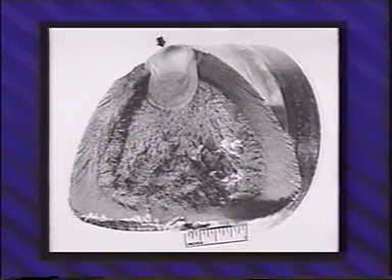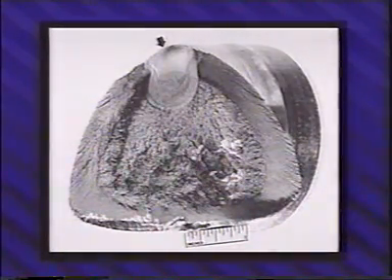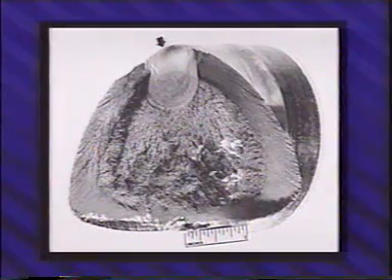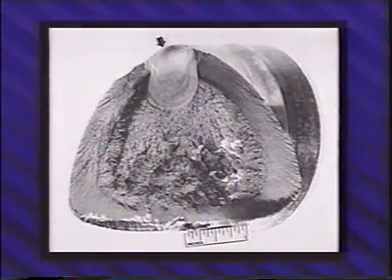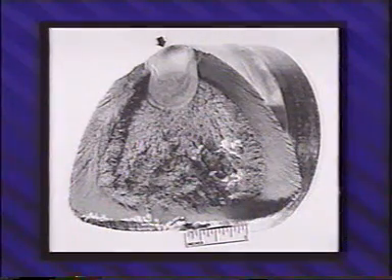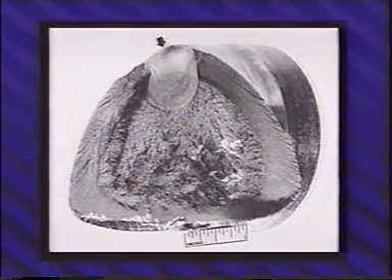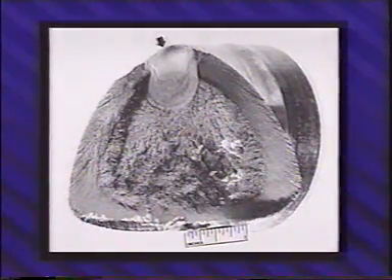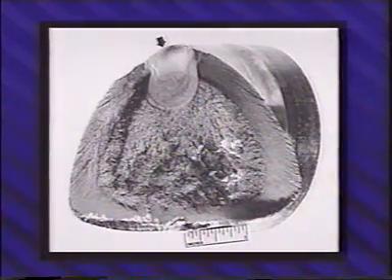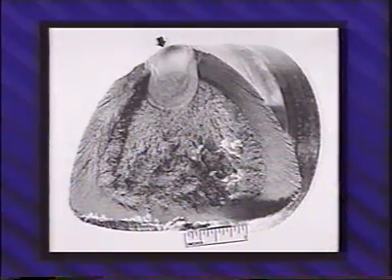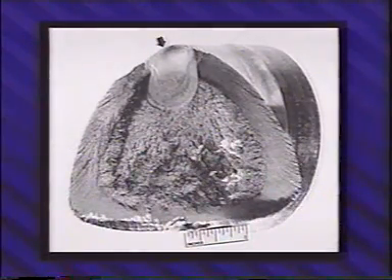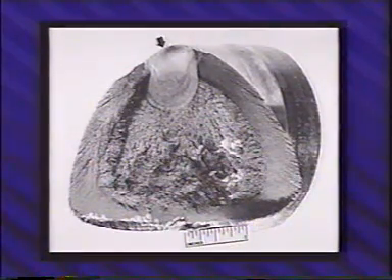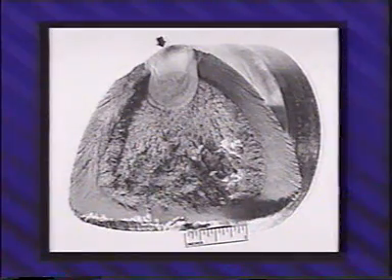In this induction-hardened axle, the fatigue origin was at the induction-hardened surface, heat-treated to about 46 HRC. The stress is concentrated in a fillet located at a change in the shaft diameter near a keyway runout. The fatigue crack gradually progressed around a large, roughly circular area. The shaft became so weakened by this large stress concentration that only one additional torsional load application was necessary to cause the final rupture. The well-defined chevron marks in the relatively hard, brittle, induction-hardened zone around the surface point toward the fatigue fracture origin. Inside the shaft, the considerably softer core shows a rough surface, characteristic of a rough tensile fracture in a ductile metal.